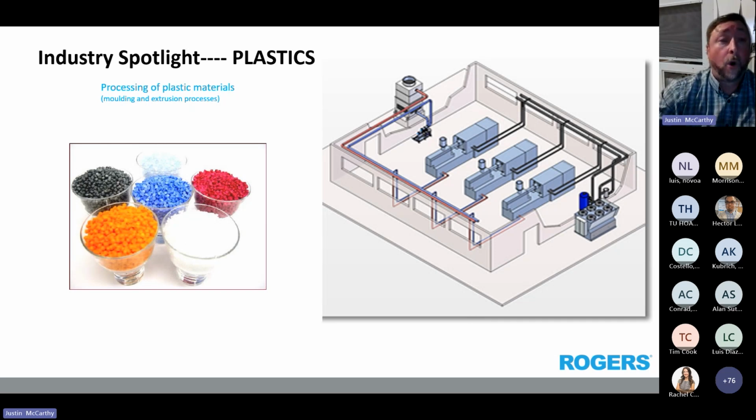So I'm talking oil hydraulics, not water hydraulics, are going to be cooled by a cooling tower just because they can get away with a much higher temperature. And the chiller is more precision for the mold.